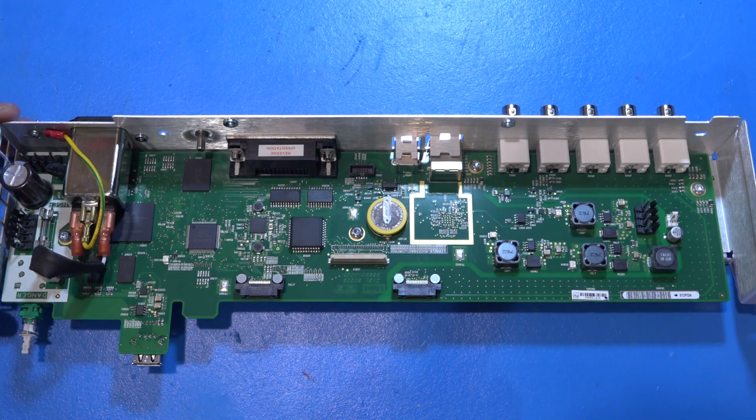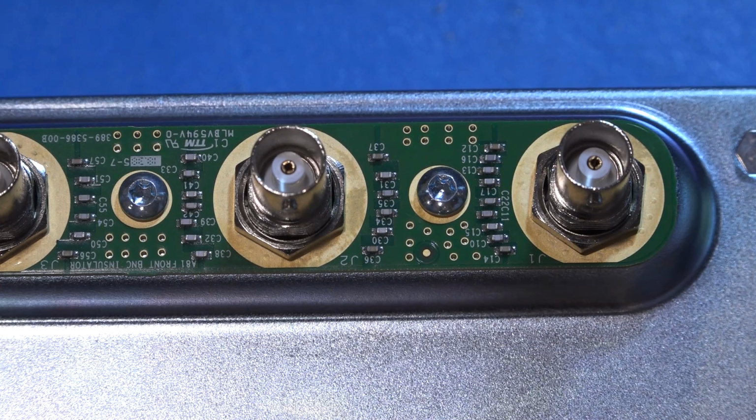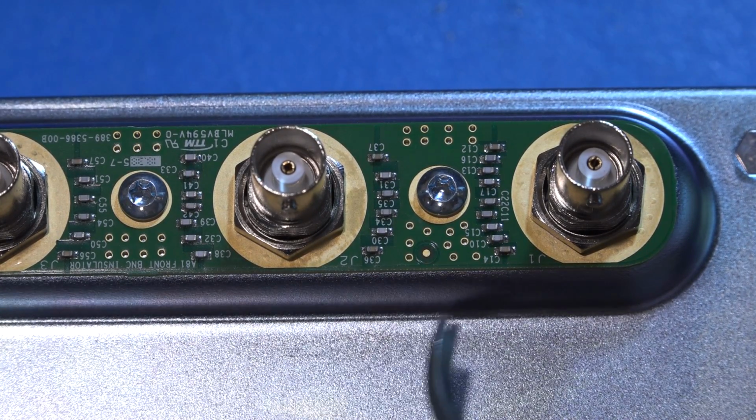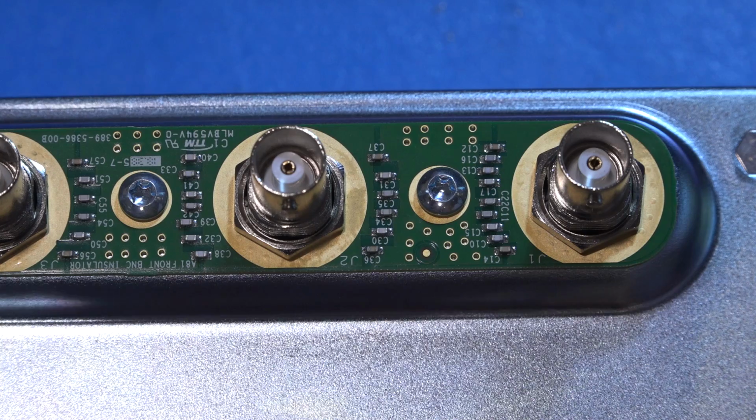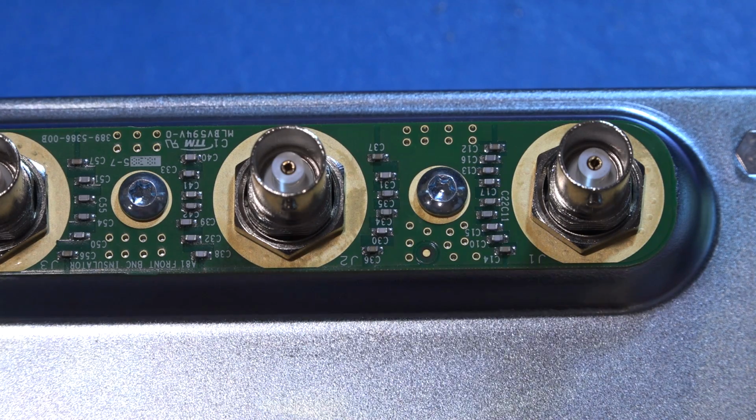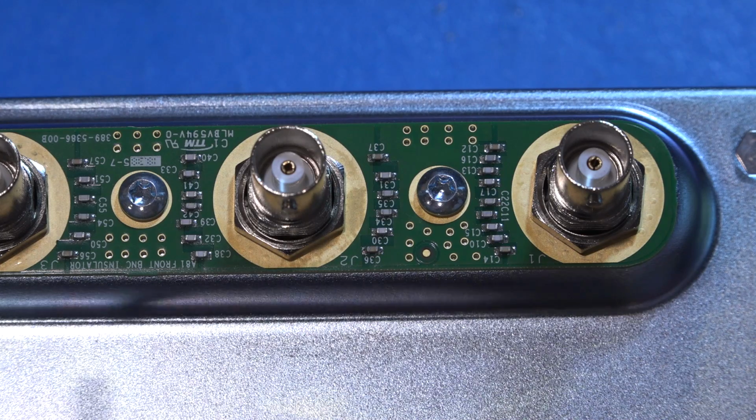Other than that, really nothing unusual. Everything's pretty straightforward. So we're going to continue putting this back together so we can see the rest of the chassis. Here is some more good example of a floating RF ground that's coupled to the chassis capacitively. You can see this is the front panel. These BNCs are DC floats compared to the rest of the chassis, but of course coupled very carefully to the main chassis ground via the stitching of this capacitor. So this is all over the place in this design.